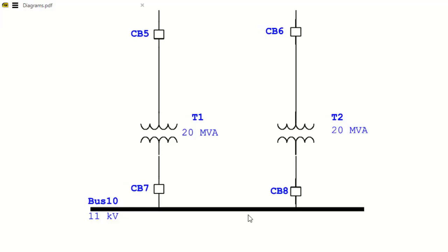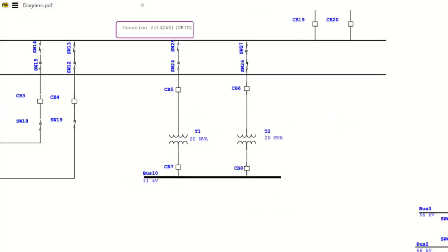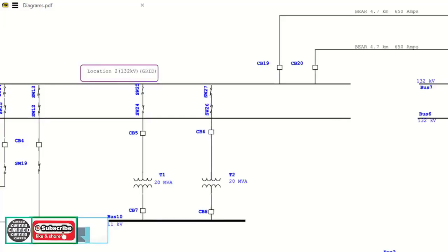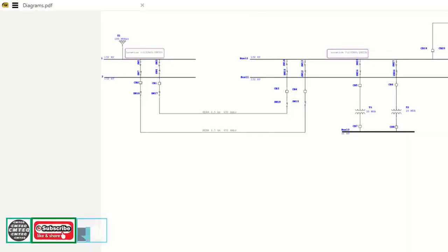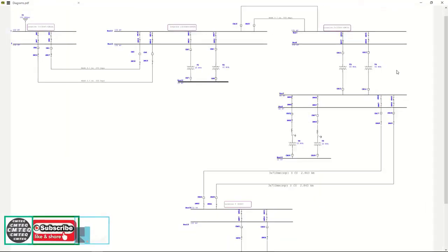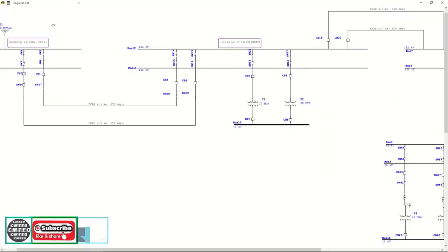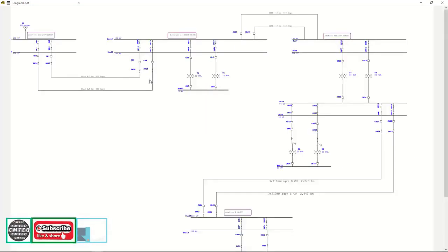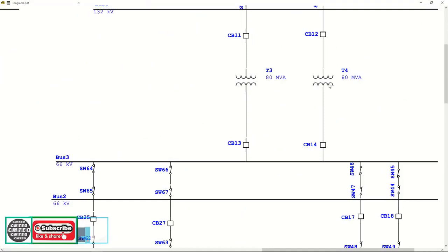If your city starts expanding, getting bigger, factories and schools, you must change these transformers. So that's basically why we have these transformers here at 80 MVA. They are big. Because if you look at it, from these 80 MVA transformers, we are going to supply an entire system down here, which is separated by two different locations. Also remember that the system overall is supplying only 100 MVA. So you have to remember that the system is supplying 100 MVA. So you're not going to have a transformer that is rated more than what the substation is actually outputting.